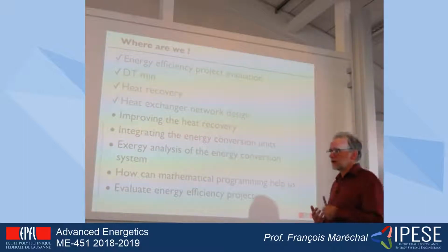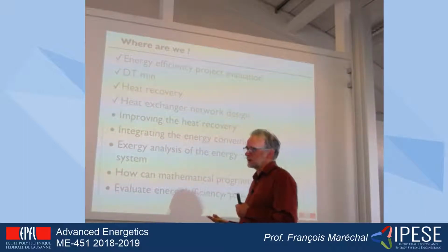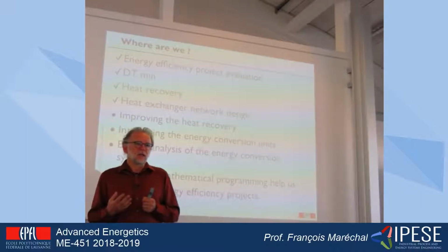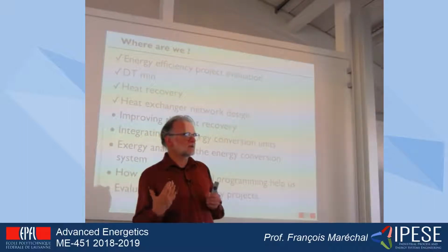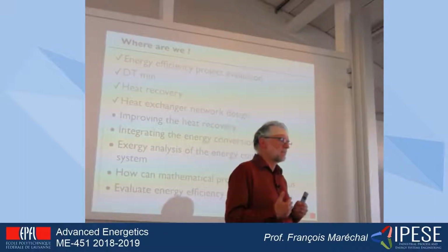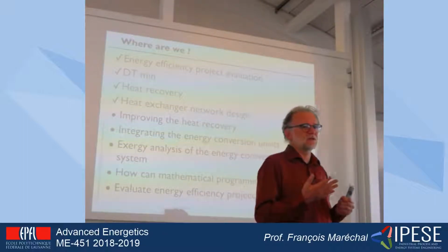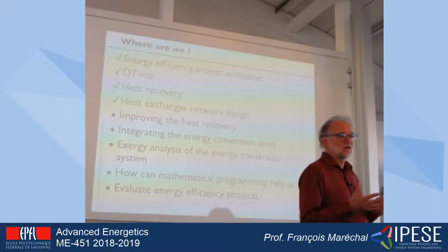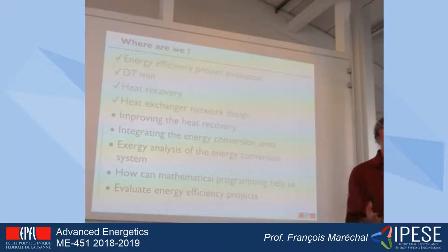So today, what we are going to do is to look at another important question. How do we define the hot and the cold streams in a process? Because if I'm not defining the hot and cold streams in the right way, I will not define the right pinch point, and therefore will take wrong decisions everywhere.